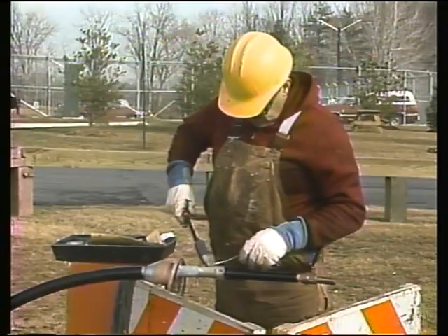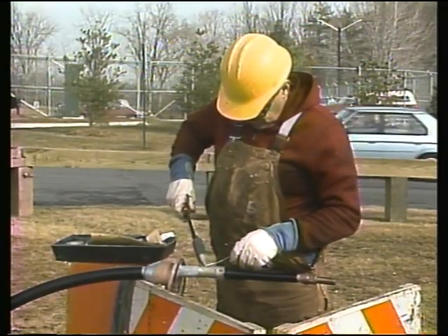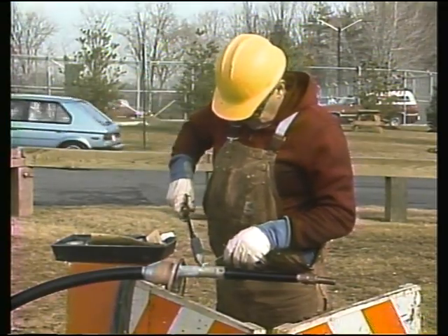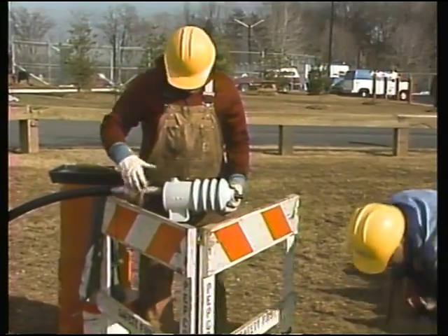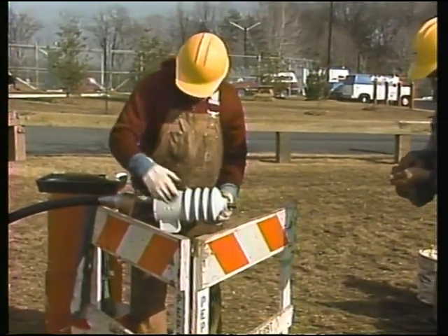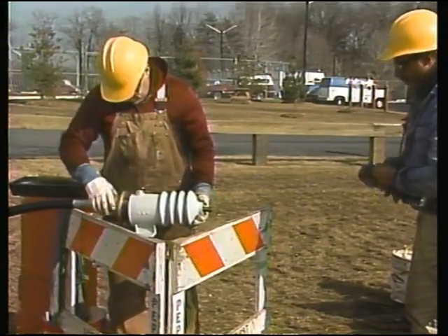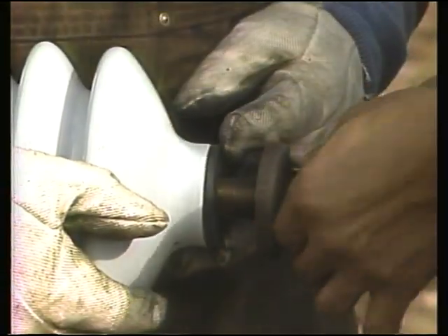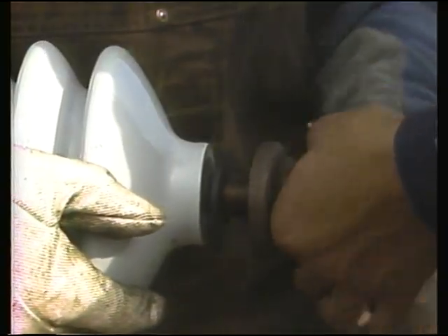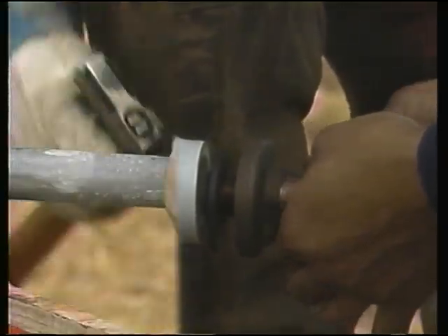He applies flux to the braided tape and then tacks the braid to the lead cover to form a ground connection. Next, the workman slips the terminator housing over the cable and connects it to the wiping sleeve. And he installs a hood nut and rubber gasket at the top of the terminator housing.